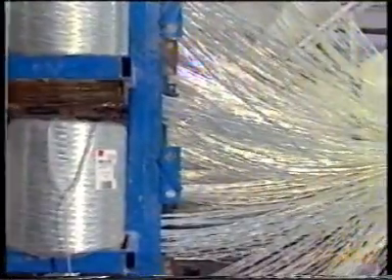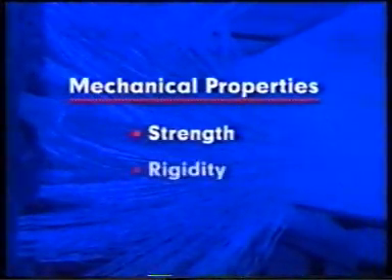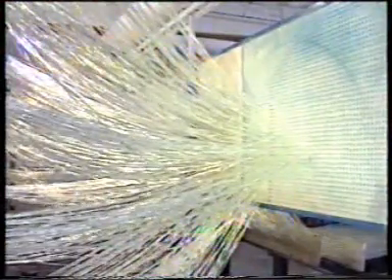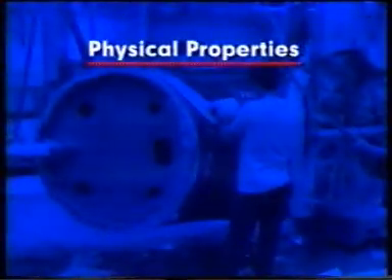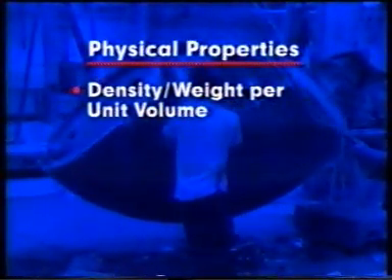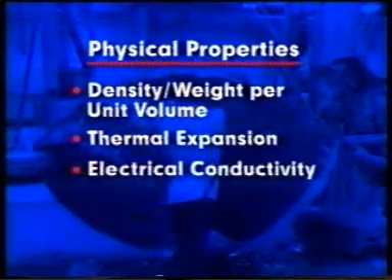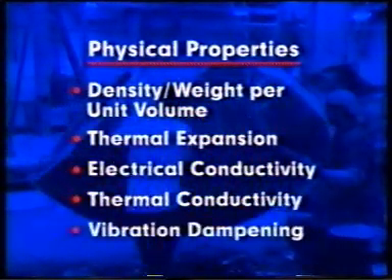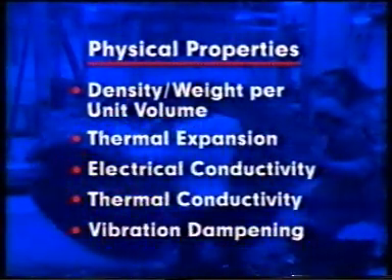Reinforcement material can significantly improve mechanical properties, such as strength and rigidity. These improvements are especially pronounced when long-oriented fibers are used. Physical properties, such as density or weight per unit volume, thermal expansion, electrical conductivity, thermal conductivity, and vibration dampening, are also influenced by the reinforcement.